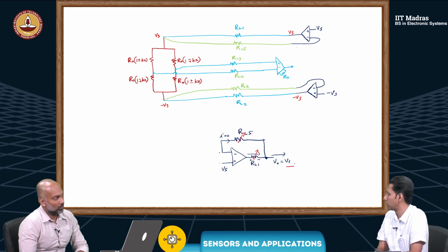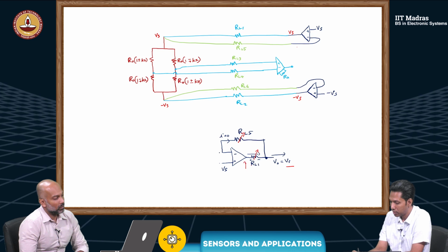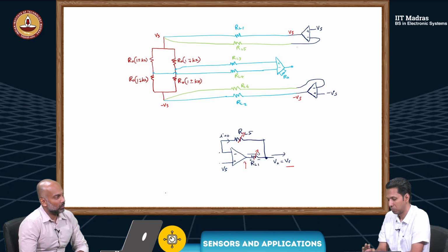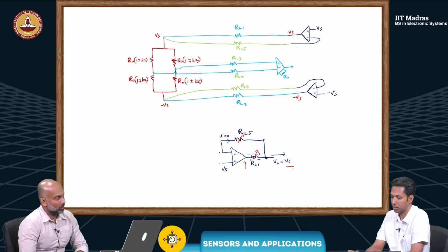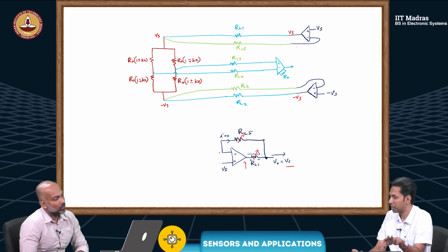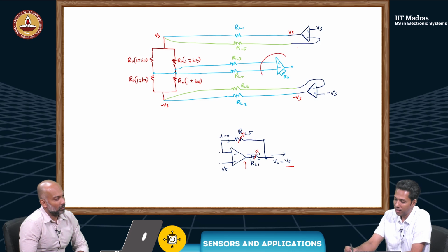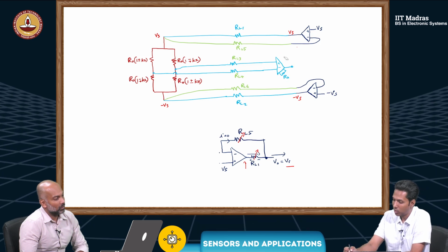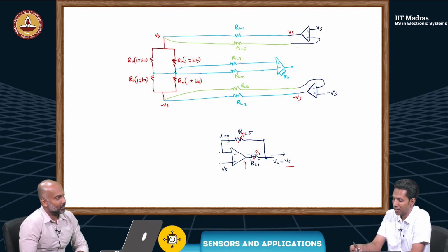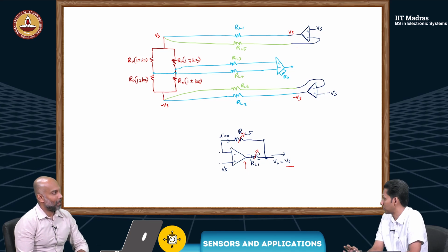Still this will be Vs. As long as this voltage is within the operating range of this op-amp, we will have Vs here. So that way bridge voltage, which is 2 Vs now, is guaranteed. And this guy has solved the problem of loading. And current drawn through RL3 and RL4 are negligible. So all problems are solved.